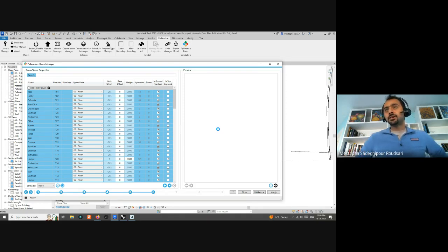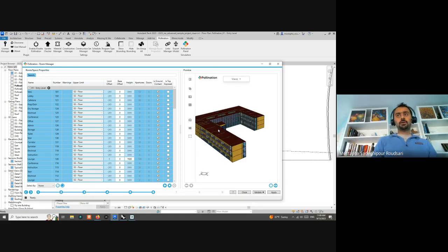So great, questions are coming in. What is computational height? So in Revit, for every level, by default, it tries to cut the plan at 0, right? That's the computational height. Then you can change this number to say where you want it to cut the plan. Depending on how your model is set up, a lot of times you have curtain walls on top of a wall, right? If you do a 0, you don't see the curtain wall, so you want to adjust it to be a higher number.